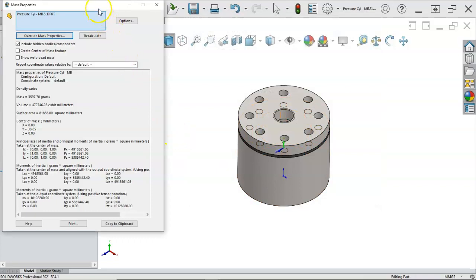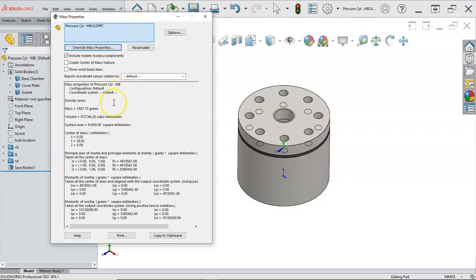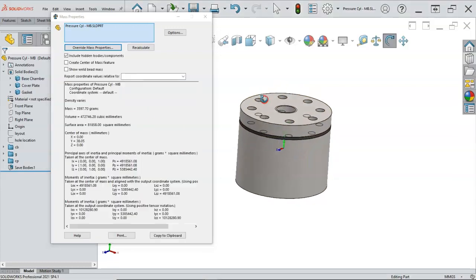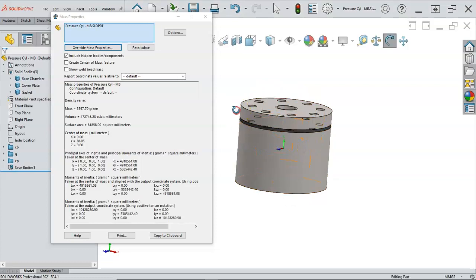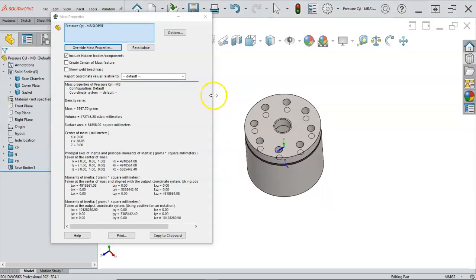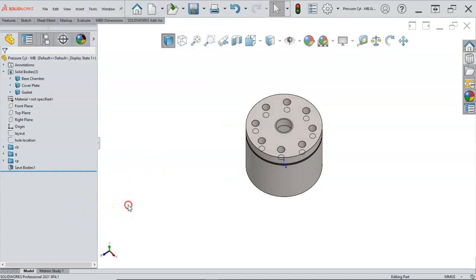So one of the things with the CSWA then is when you're taking the exam, they're going to ask you for these values. If you've gone through and applied the materials, my number should match your number pretty close. Or if we are calculating for the center of mass, yeah, this one isn't as exciting, but the center of mass of 38.5, and if we rotate around, we can see where that location is. So those should also match up pretty close. All right, we're ready for the drawing.